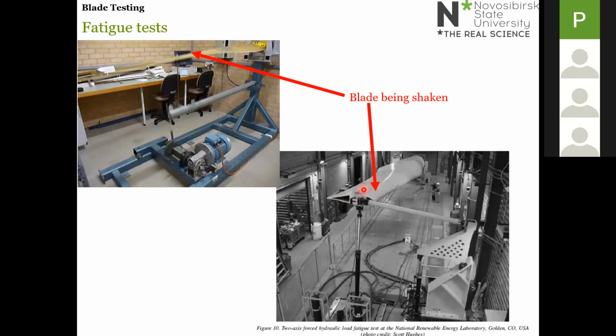And again, this is really critical for the structural integrity of the blades, and the international standards from the International Electrotechnical Commission that govern wind turbine safety make it a requirement that each new blade design is fatigue tested.